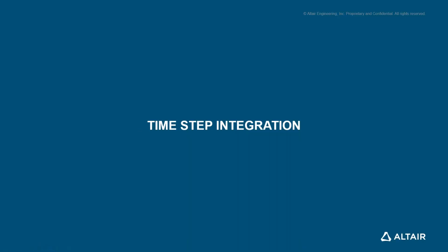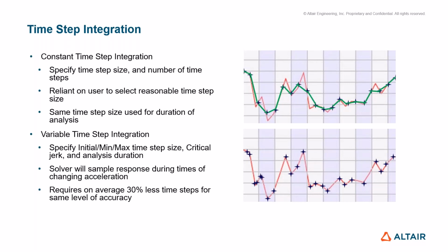The last topic I'm going to jump into here before we move on to Andreas's demo is the time step integration. Essentially in SView, we have two different options. We have a constant time step integration, which we kind of introduced in one of the earlier slides, where we specify the number of time steps we have and the increment between each time step.